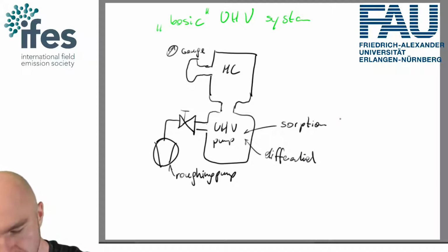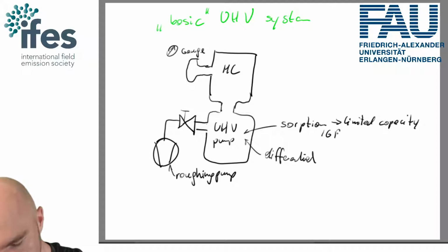Sorption means limited capacity. And sorption pumps would be ion getter pumps, non-evaporative getter pumps, titanium sublimation pumps, things like that.